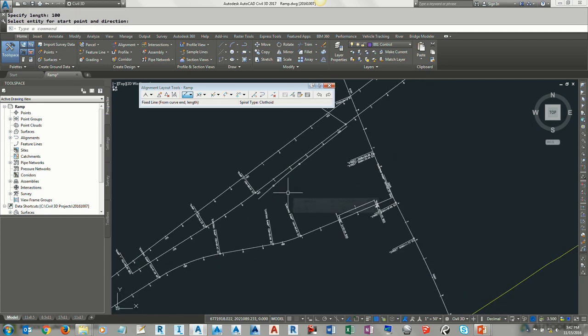So now, that curve is huge. It's very slight. So you realize the style I am using is production style. Everything is white. I have no idea, did I really create a curve in the middle, or was it a tangent? So that's where analysis styles come in, and they display curves in different color. But anyway, so I got this. Then the last piece, to make sure the curve is tangent here and tangent here. By the way, this piece that I added, the small piece, is not actually part of the alignment. I'm going to ultimately get rid of it.